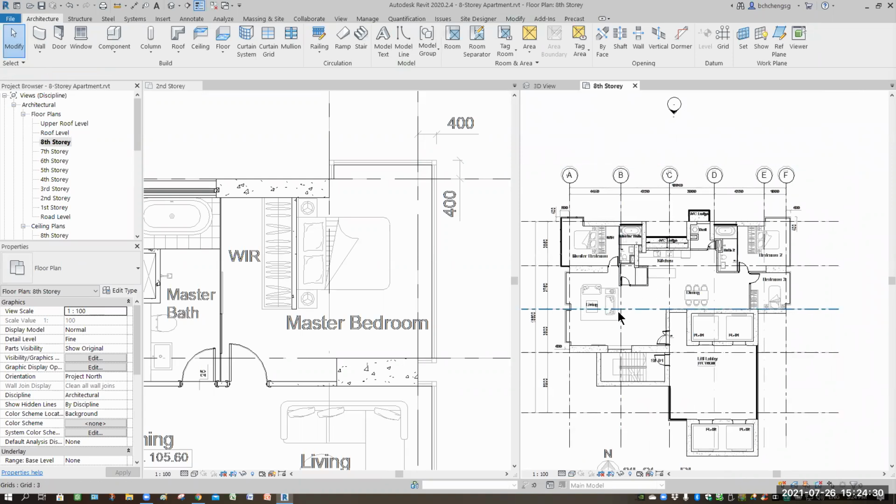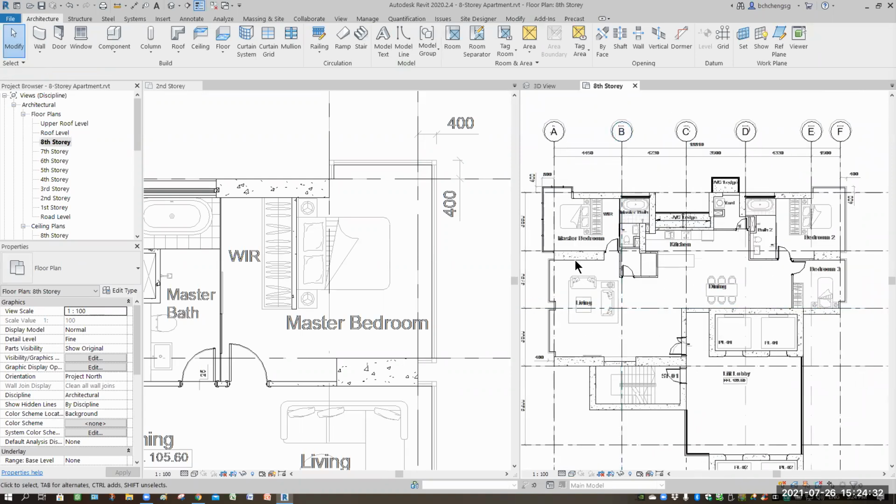If it's very big and you insert aircon here, those ASCMV in future, when they blow air, might not be able to cover this area because there's a range or distance. If you install the fan coil here, it will blow up to here and might not reach here. So certain places are not cool.